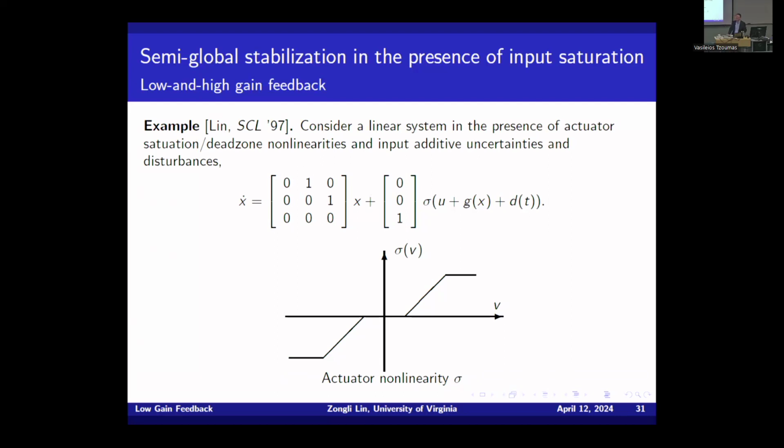Sorry, Chris. Yeah, no, that's fine. Now, maybe critically here, you haven't gotten to the delay part yet, right? So perhaps on slide 30, you were exploiting the infinite gain margin from LQR, but if any of those state measurements were subject to a little bit of sensor delay, then you would have practical issues implementing. Exactly. Yeah. So in other words, this part doesn't carry over to delay. That's why I mentioned it earlier.